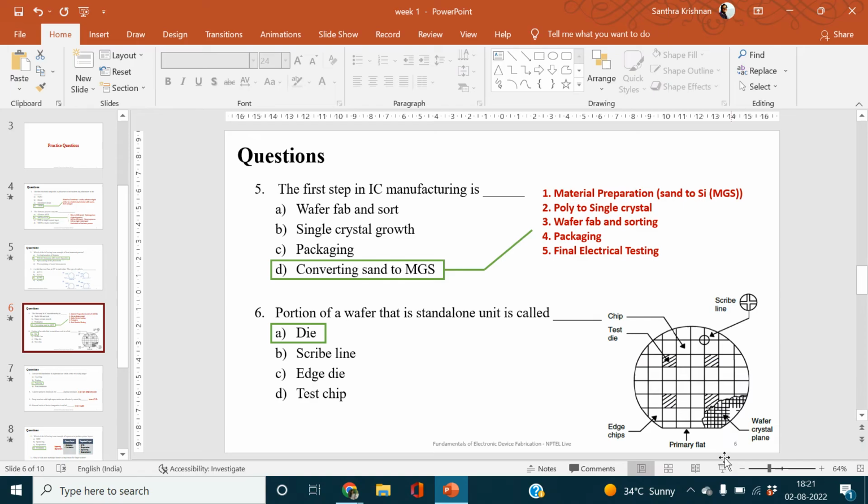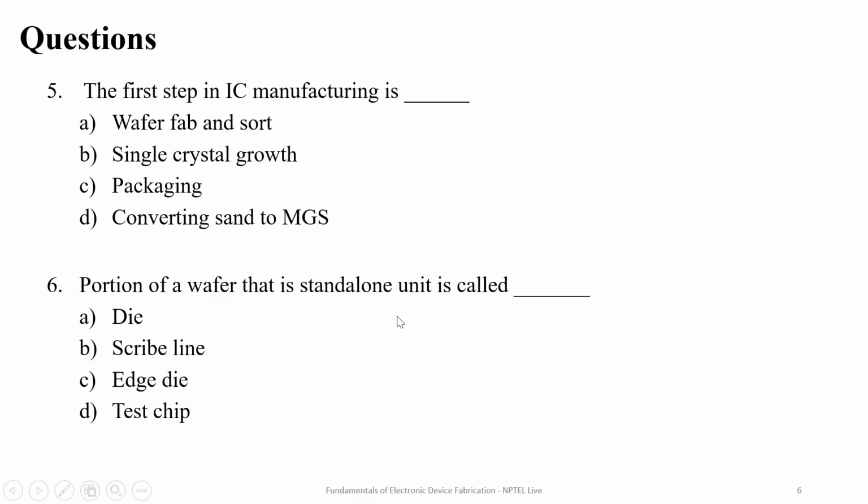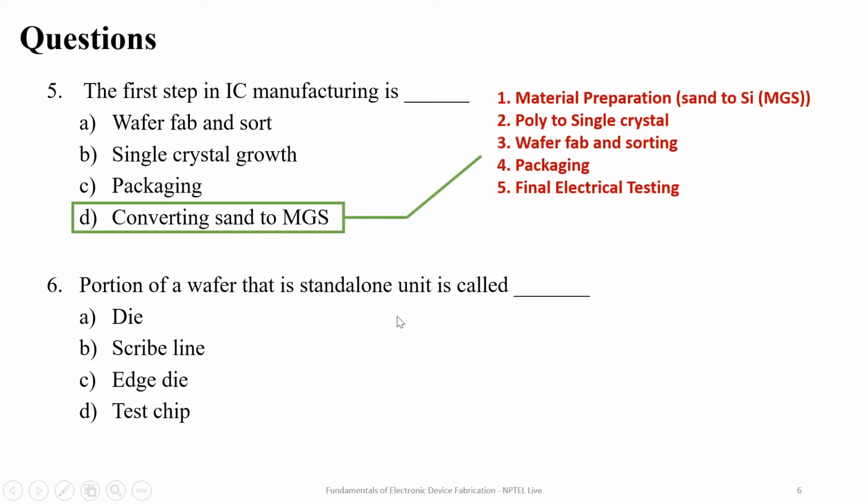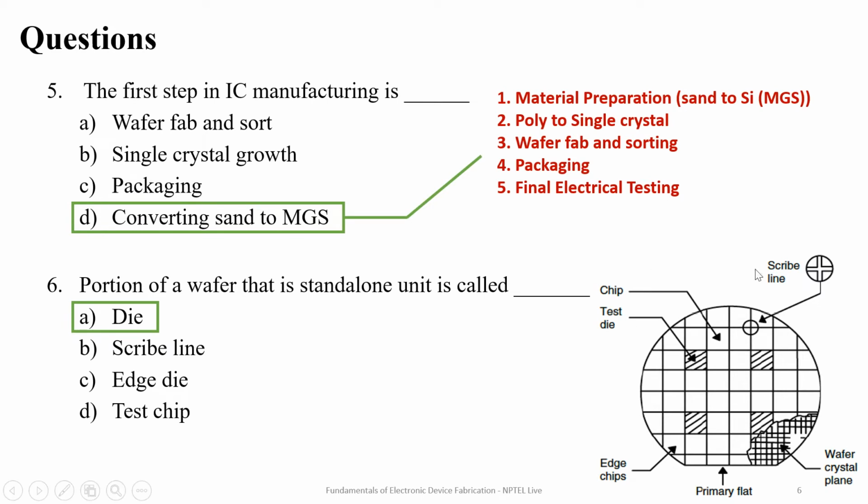So one thing is that during processes like Czochralski and float zone, we will be getting a crystal wafer that is circular. And the other thing is that these are very thin wafers, right, very, very thin. So if it has sharp edges, there will be a possibility of stress concentration, and while handling there is a large possibility that it will break. People who have used silicon wafers here might understand how fragile these things are. So to avoid this also, they will have rounded edges.